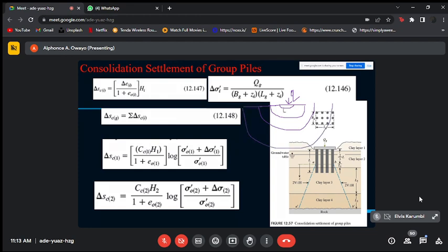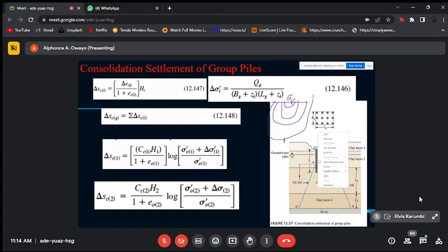So this would be 0.9 Q, 0.8 Q, and the point is the influence of that load reduces the deeper you go inside the soil, in terms of bulbs. Maybe I've not done it very well, let me try again. Q, like this, and there are usually bulbs. But the point is, down here the influence of that load is very small, and there are certain formulas for how to do that. So nothing new. If you relate it to exactly what you've done, then it should be very clear.